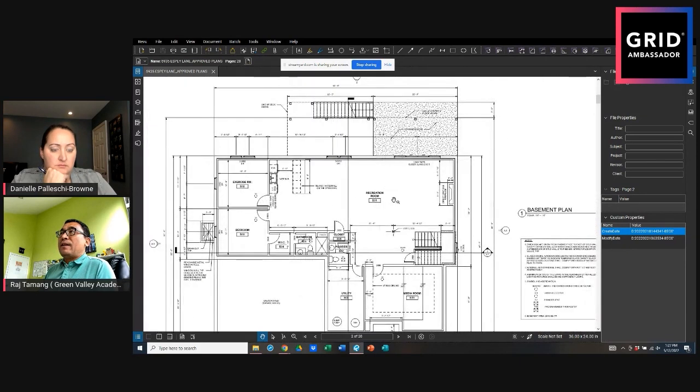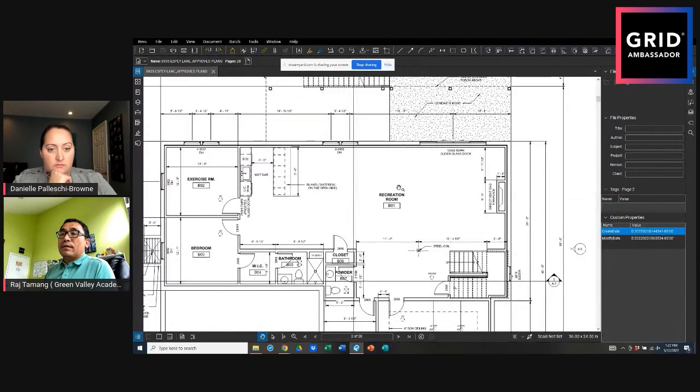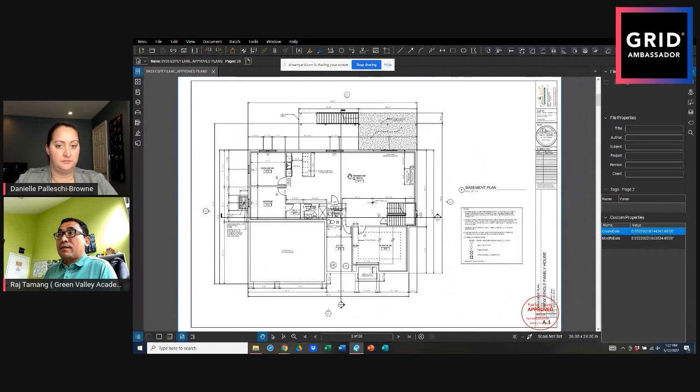And you're asking, what is that information here? It says 8-inch concrete wall. This is structural information. You have to go to the structural drawing, because this is the basement plan, an architectural plan. Any structural information, like how thick the concrete wall is, what the reinforcing is, what the footing thickness is, all that information you have to get from the structural drawings, right? So right now we're in architectural only, which is a basement plan.